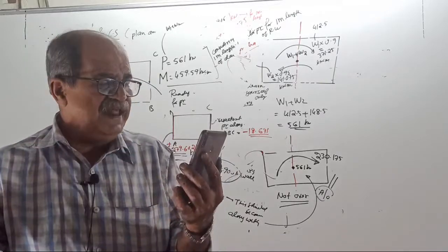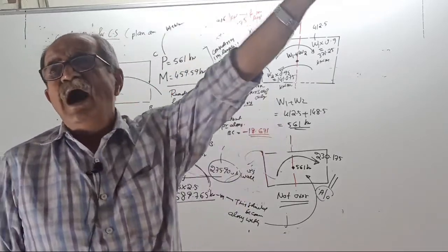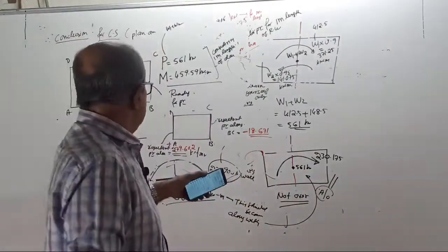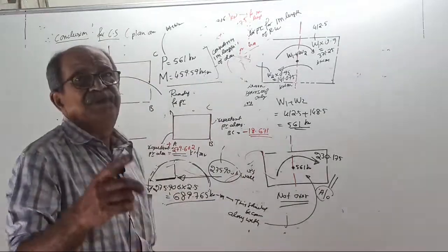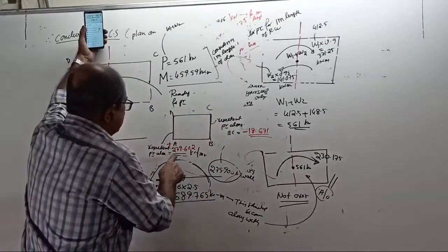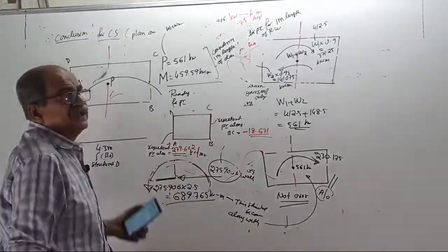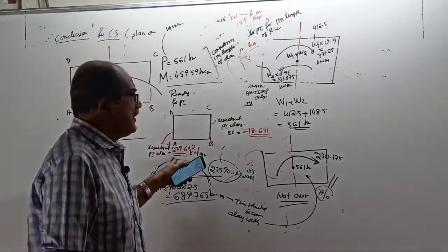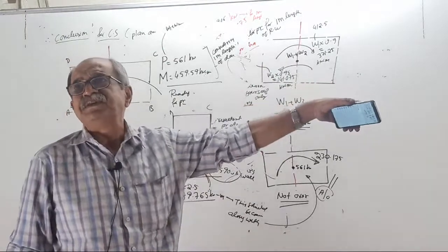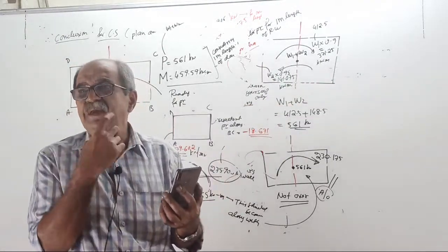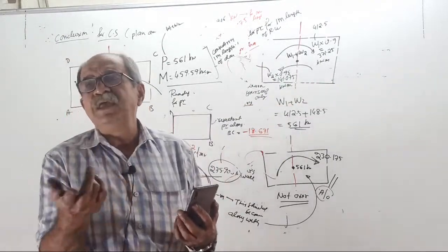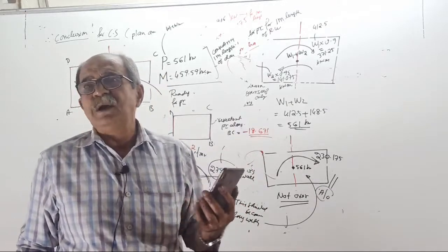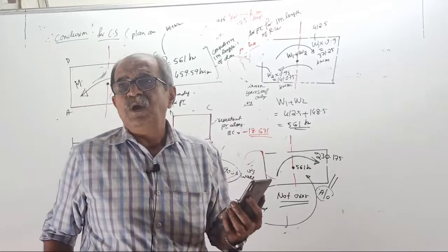That's all strength of materials. What to do? RCC, you increase the base width. Now we do not know the SBC of soil. Maximum pressure came 279. If SBC of soil is around 200, 250, it is unsafe on pressure. And that side, negative pressure came. Tomorrow you will know this in a systematic way: calculate the resultant eccentricity E and compare with B by 6, one-sixth the length.